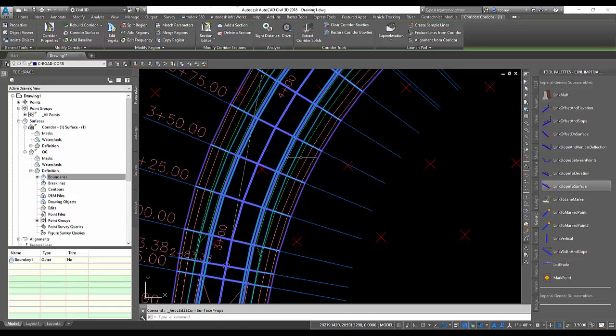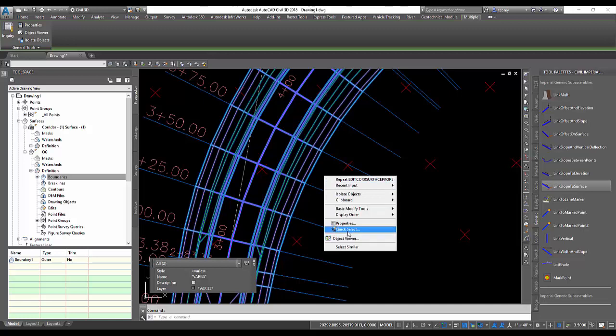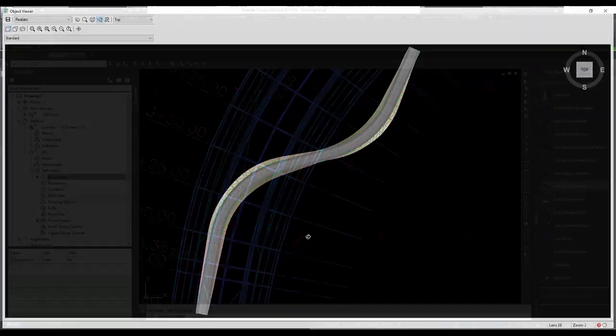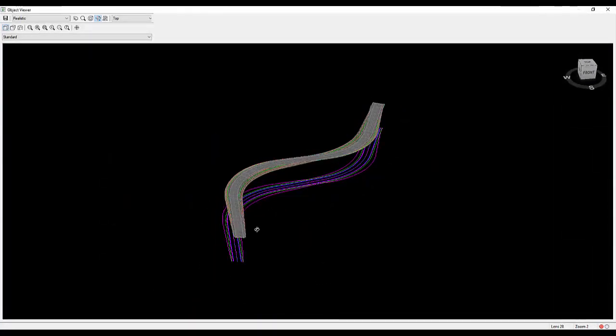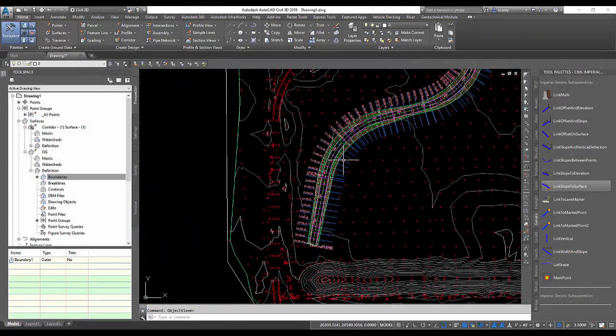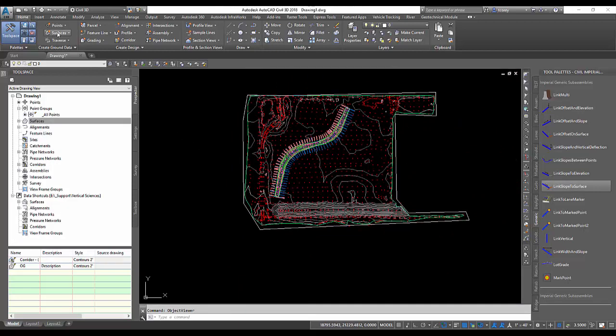And now I have a surface for that corridor. Okay. Once I have that surface, and I already have the original ground surface, now in order to calculate the earthworks, I would go on the Home tab under Surfaces, create a new surface.